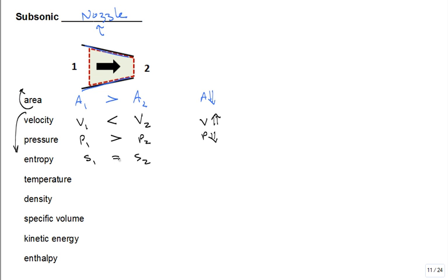So it's isentropic. So this S is a constant. It's isentropic flow. That's the traditional assumption. Now, you can define an isentropic efficiency for a nozzle to account for some friction effects, etc. But let's just say we have isentropic. Sigma is equal to 0, no entropy generation, S constant.